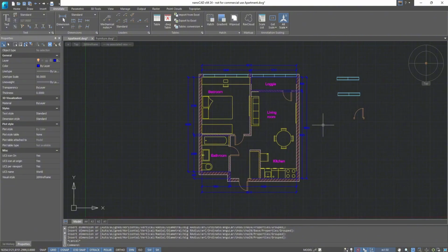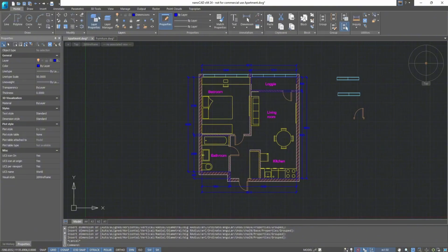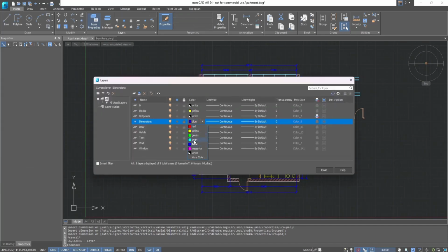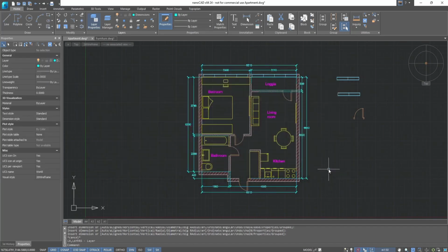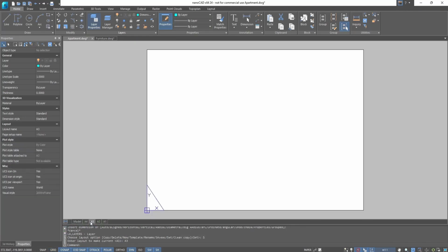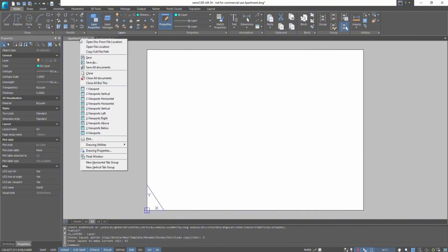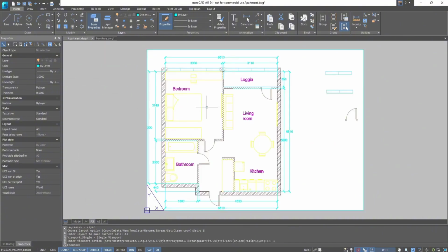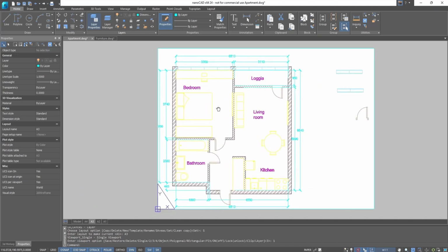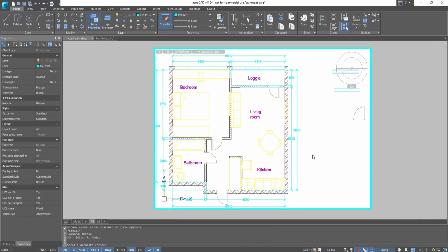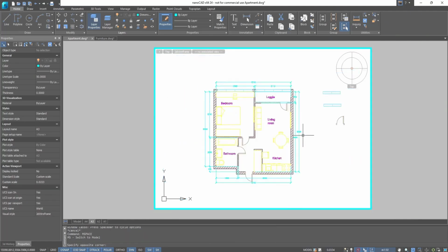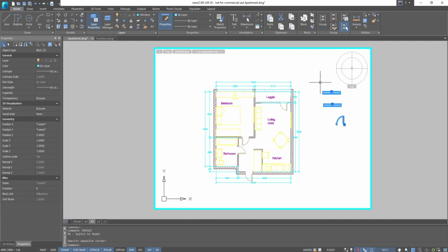Blue is poorly visible on a dark background, so we will change the color to cyan. It looks great. It remains to transfer this drawing to the sheet space. Go to the tab of the format you need. Mine is A3. Right-click on the project's name and choose Viewport. You can put the canvas as you like, closer, to the left, and so on. Double-click on the sheet to edit it. We don't need it here, so I delete it.